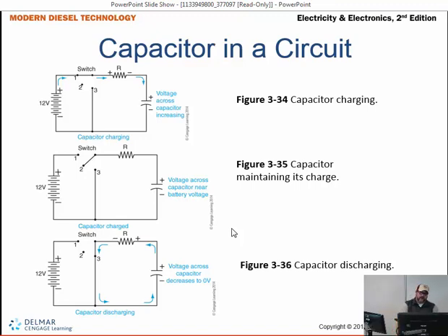And it's DC voltage, so it can do all sorts of damage to your muscles and body. And so it's unexpected, because we think, oh, I unplugged it. Certainly, there's no battery in there that could hurt me, but this capacitor lives in there. And so we'll talk about that. Capacitors actually getting discharged hurts. It's a pretty good sting.